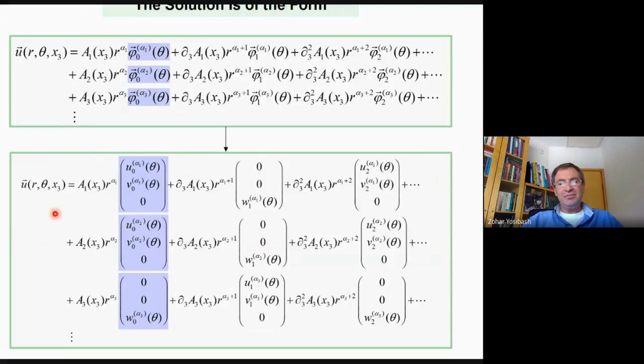So in elasticity, if, for example, we are looking at the first eigenvalue, then what you see here in blue is the two-dimensional solution. So in two dimensions, you have the so-called u r and u theta, which are a function of theta times r to the power of alpha 1. Now I switch to alpha because in elasticity, we have the Lamé constants, which are lambda, so they may interfere. And this is what we refer to as mode 2. So this is associated with K1. This is associated with K2. This is associated with K3, and so on.